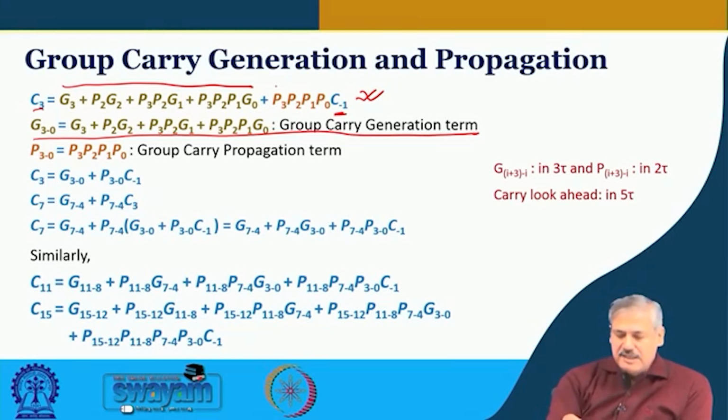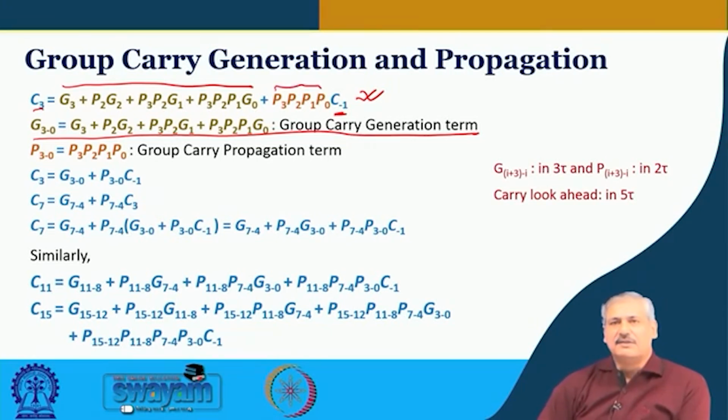And this particular term in a different color, when this is 0, then even if there is a carry present at the input of this block, it will not get propagated. It is exactly similar. You will see the equation and other things that we will get is exactly identical to the one that we had seen in case of fast adder development, isn't it?